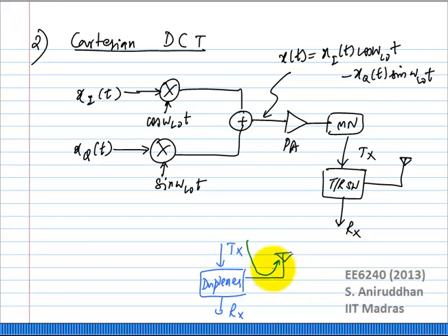At the same time, it allows the RX signal to go from the antenna port to the RX port. So it has a frequency dependent behavior. And the third thing you obviously need is to make sure there is very little transmission from your TX port to your RX port. You need very good isolation from your TX to RX. Is that clear? And we are soon going to see why we need that.